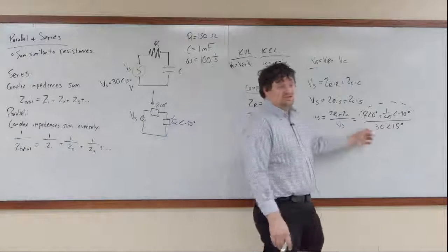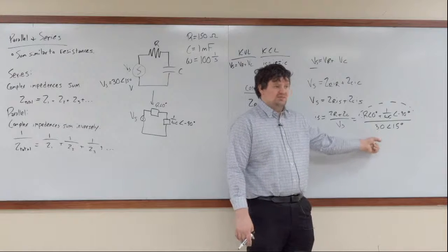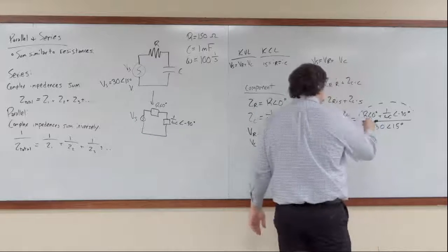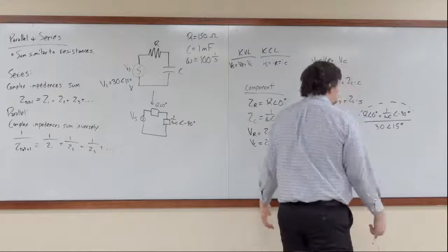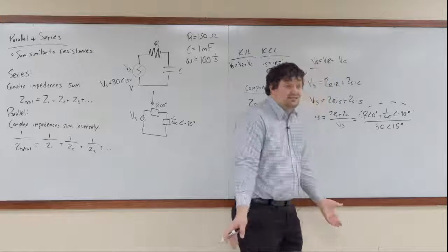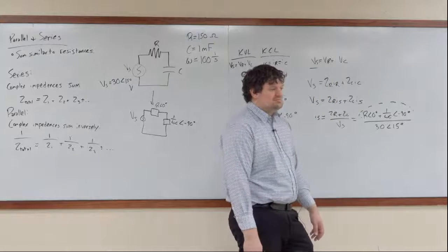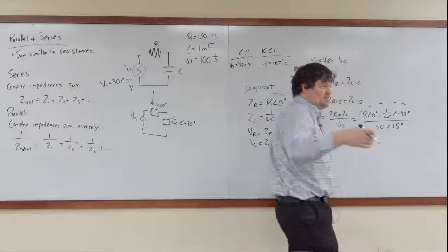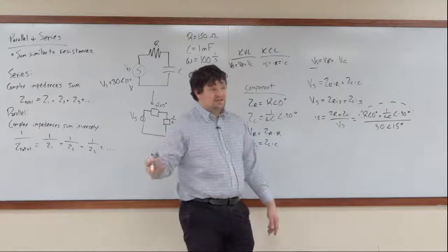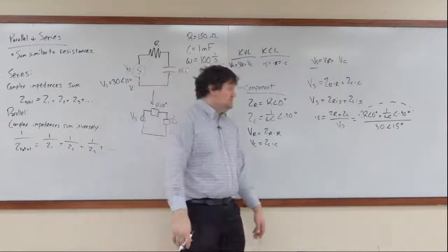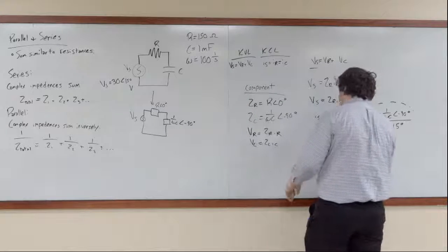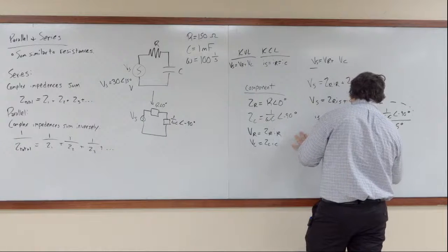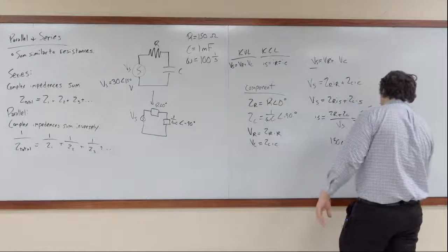We're going to be able to combine these. So we have talked about adding phasors before. We got to do that now. So let's go ahead and add phasors. So here, R at an angle of 0 degrees. How do we write that? 150 times cosine of 0 degrees, right? Yeah. Plus 150 times j sine 0 degrees.